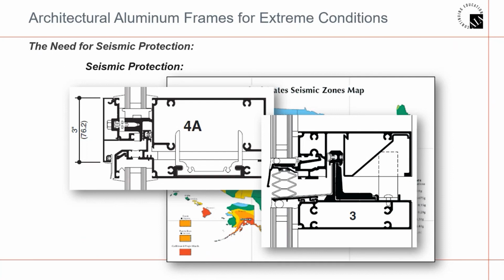Most curtain wall manufacturers can simulate the performance of the systems based upon story drift value for each project. It is best confirmed early with the manufacturer that your design will perform as anticipated with their individual system. But again, in seismic areas, unitized systems allow for greater movement than your typical stick system.